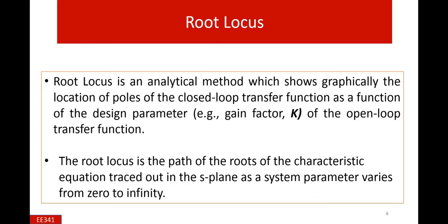A more mathematical and understandable definition is that it is the path of roots of a characteristic equation in the s plane when the system parameter changes from 0 to infinity. When the open loop transfer function is given, we find the closed loop transfer function, and the denominator of the closed loop transfer function is the characteristic equation.